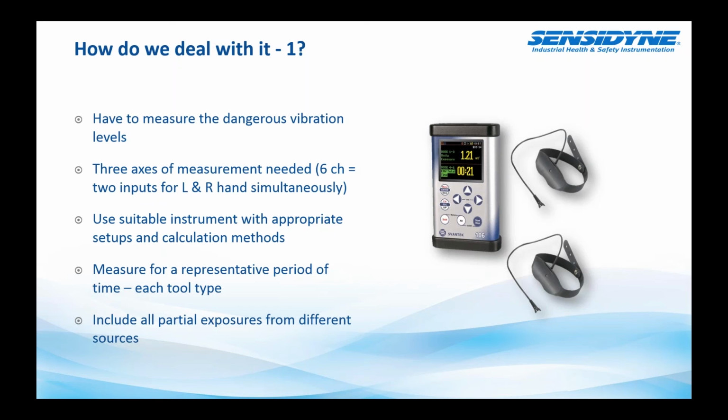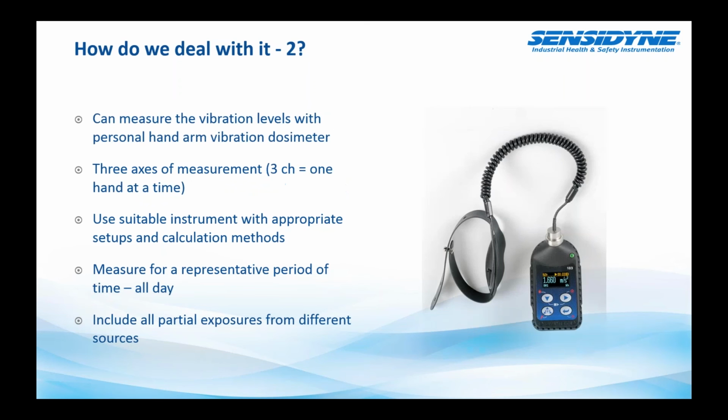so you can think perhaps of that previous instrument as being the equivalent of a handheld sound level meter. Somebody is there to operate it and to make the measurement, but just like we have noise dosimeters that a worker can wear without the need for any supervision, this is an example of a vibration dosimeter specifically aimed at hand arm measurements. The worker puts the hand strap on a short length of cable and the small body of the accelerometer fixes to a strap on their arm.